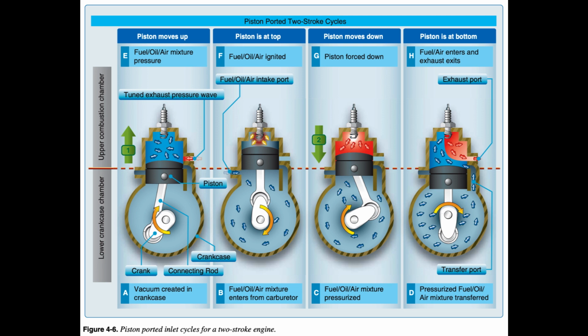Overall, the two-stroke exhaust system for a WSC aircraft is a specific design and must be matched to the engine to operate properly and obtain the rated power. It also reduces noise and directs the exhaust to an appropriate location. Exhaust silencers can be added to reduce noise, but additional weight, cost, and slight power reduction are the byproducts.